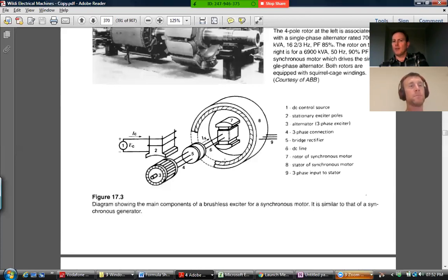Obviously, technically the speed that you spin this thing also affects the excitation voltage. If you slow the spinning down, you reduce that excitation voltage as well. So that relationship between the exciting current and the exciting voltage is actually for a given speed. But generally speaking, we're talking about fixed speeds, because for generators, definitely, normally you're sitting with your 50 hertz, come what may. For motors, we might have speed controls on these things, so it's not necessarily 50, and there are some equations that look at that, but it's beyond the scope of what we need.